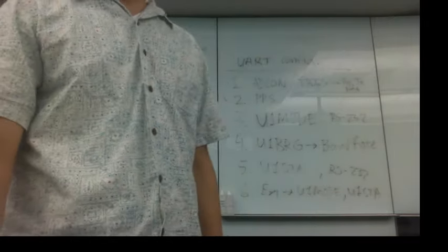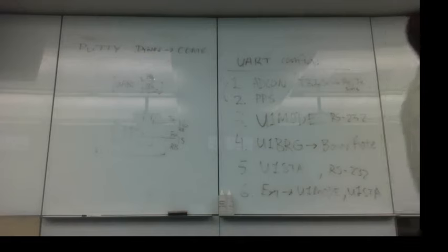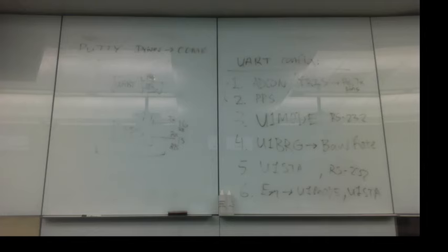So, parity and data selection bits. We're going to be using 8-bit data mostly. You can send 9 bits of data at a time, and I could see that being useful if you're sending and receiving signed numbers, basically, or if you just want to send more information, you have an extra bit. But we're just going to be sending bytes at a time. For characters, how many bits are in an ASCII character for UTF-8? 8 bits. So if we're sending and receiving characters, we'll probably just use 8 bits.